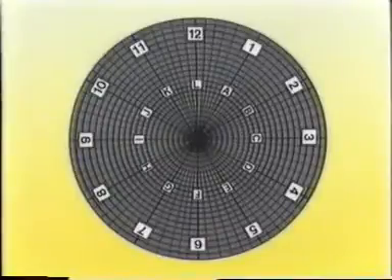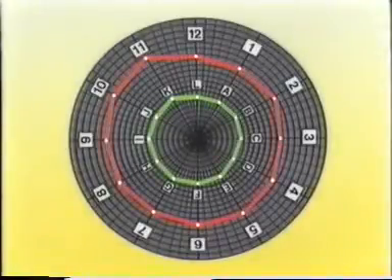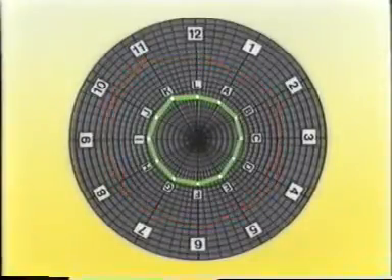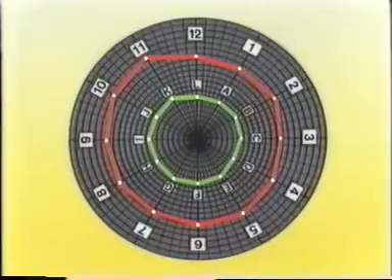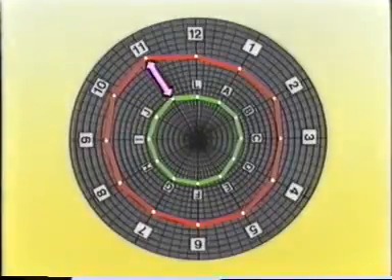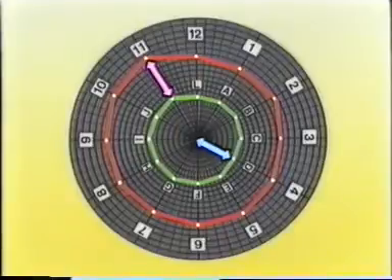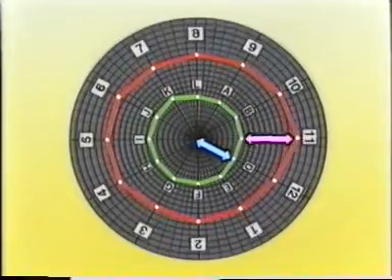The results will look something like this. The outer line indicates the radial runout of the tire, and the inner line indicates the radial runout of the wheel. As we said before, if you move the thickest part of the tire to the point where the center of the wheel is closest to the rim, the radial runout will be reduced.